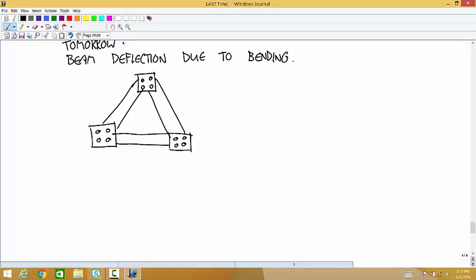But I'm just saying that this gusset plate system, if you unhook the bottom, it's not going to flex like a pin joint. Right. That's all I'm saying. And so that makes it a statically indeterminate system. And to really carefully calculate that, you'd have to use a statically indeterminate approach.